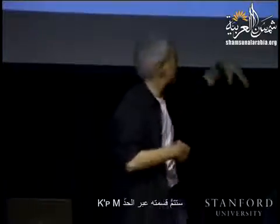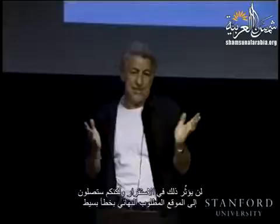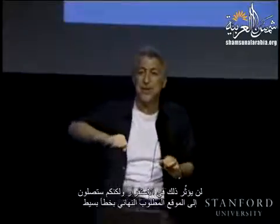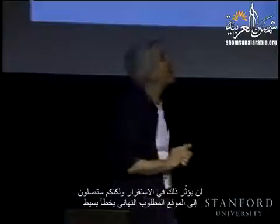So you will have just a sort of constant torque offset that will be divided by your Kp prime times m. So that's not going to affect the stability. You will just reach the final goal position with little error. So what is the effect of m minus 1 and m hat?